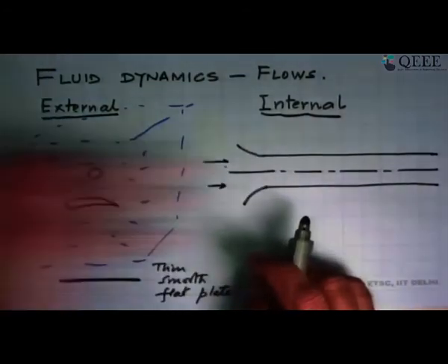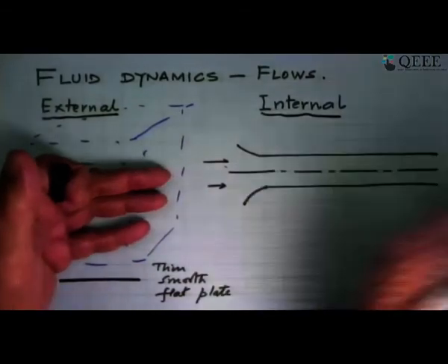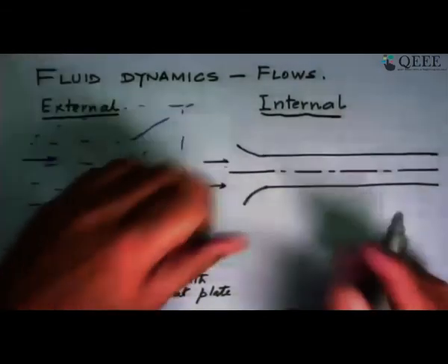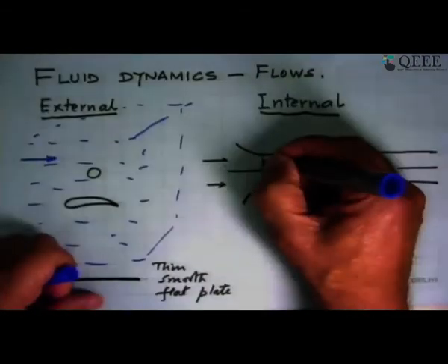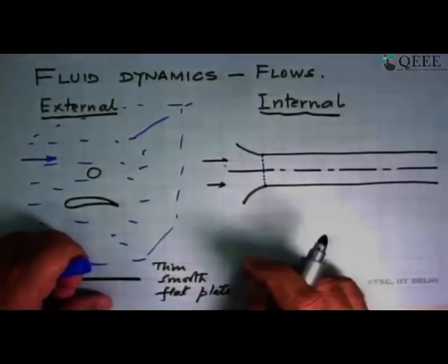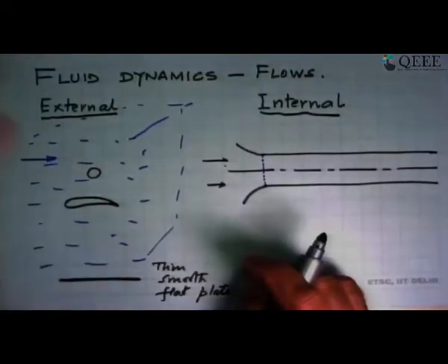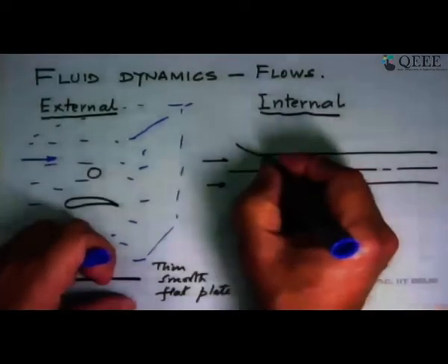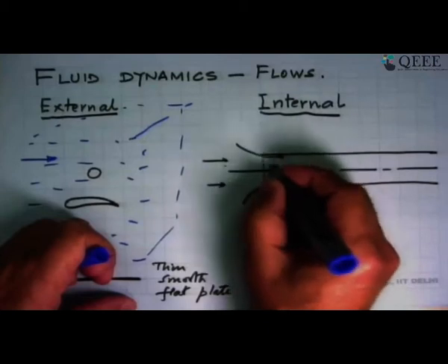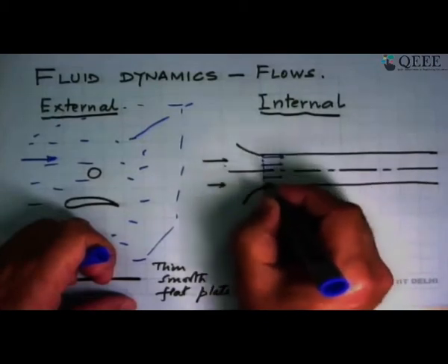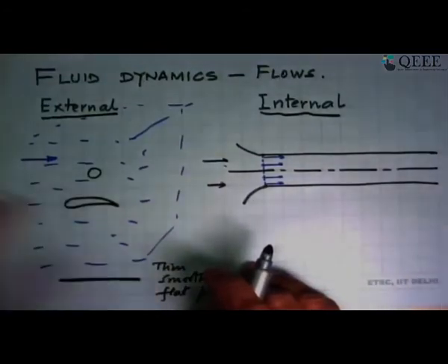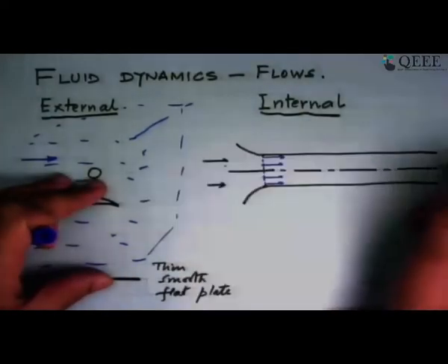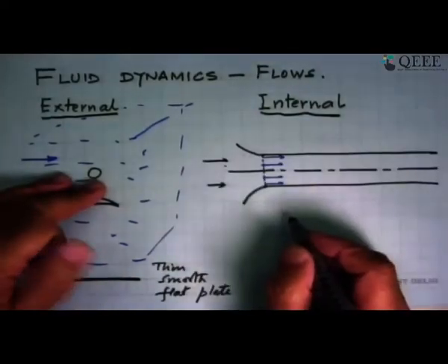This could either be pumped from this side or be sucked at the other end, but we have made a very nice smooth entry which gives us the condition that when the tube begins, which is some physical point somewhere on the tube, the velocity at every point is the same, the local velocity. This is an assumption, an idealization. And we are going for this idealization because this lets us understand what happens inside this tube.